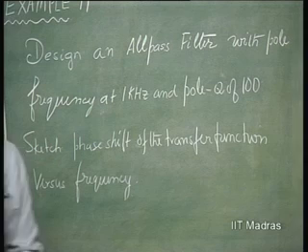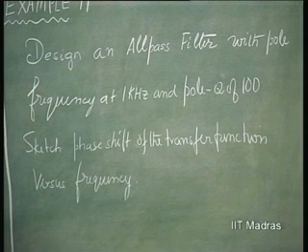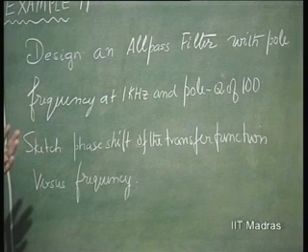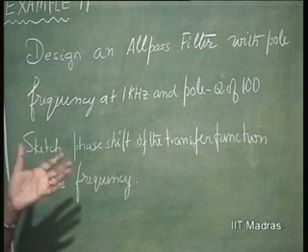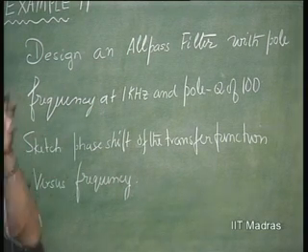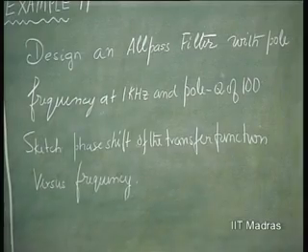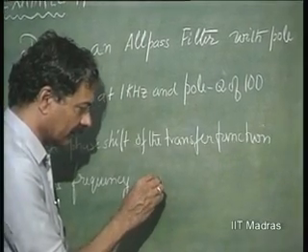Here it is primarily used for obtaining phase shift variation with respect to frequency. So, we will see how such a network which passes all the frequencies without any attenuation, or with the same amount of attenuation or amplification, but will subject each frequency component to a certain phase shift. So, such a transfer function, second order transfer function, will look like this.